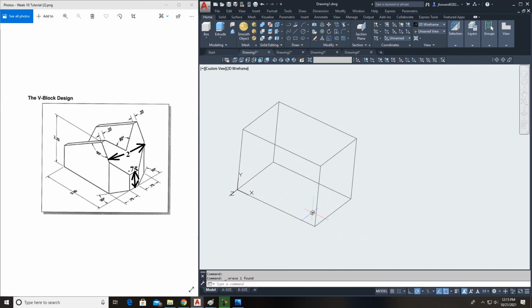So with that done, I want to take my line, and I'll come right up through here, straight up, 0.75, enter. And I'm coming back at it's showing a 90 degree. This right here, actually, folks, is a 30 degree line right here. So this is a 30-degree line.